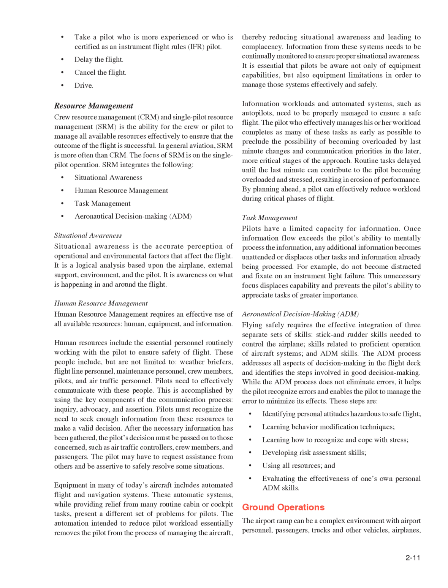Information workloads and automated systems, such as autopilots, need to be properly managed to ensure a safe flight. The pilot who effectively manages his or her workload completes as many of these tasks as early as possible to preclude the possibility of becoming overloaded by last-minute changes in communication priorities in the later, more critical stages of the approach. Routine tasks delayed until the last minute can contribute to the pilot becoming overloaded and stressed, resulting in erosion of performance. By planning ahead, a pilot can effectively reduce workload during critical phases of flight.